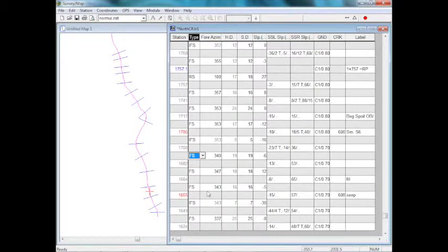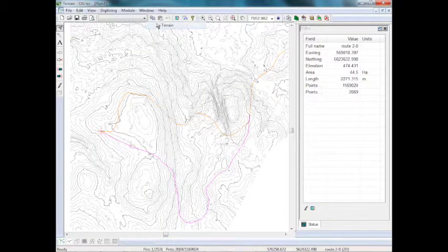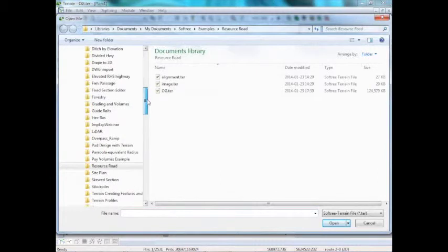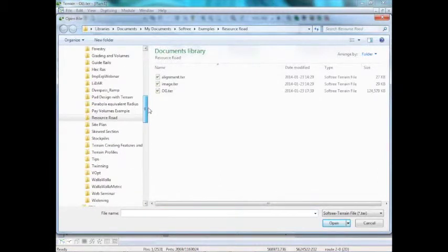Once we've got our data into this file, we can go over to the location module, and we can create a design using the side shots as cross sections. The other thing we can do is go to the terrain module, and read in the survey with side shots and create a surface. I'll just show you one. I won't go through the details, but essentially those side shots do define the surface.